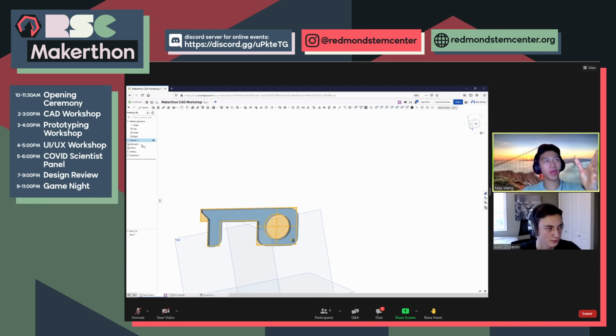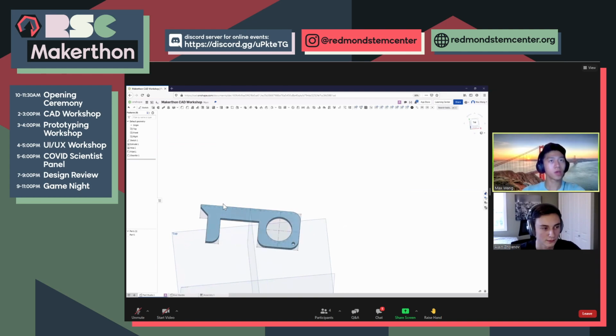This extrude depends on that sketch. So if you move that sketch after this extrude, then it doesn't make sense, right? Because you can't extrude something that doesn't exist. So this has to be before here. Just make sure you understand that this is a really important way you can manipulate your part studio. Great. Let's move on to the assembly.